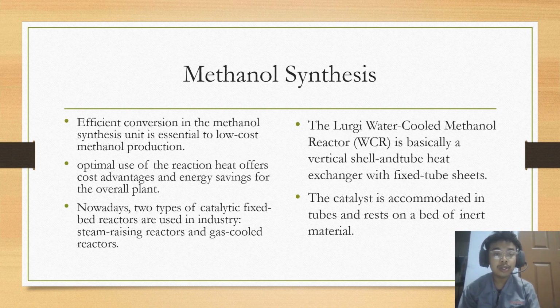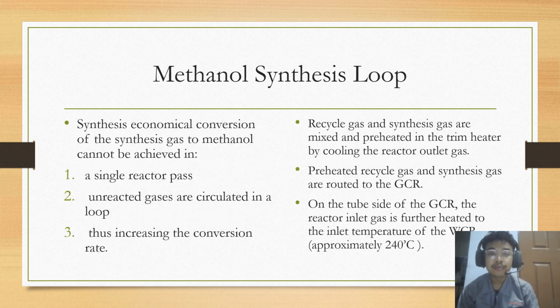The optimal use of the reaction heat also offers cost advantage and energy saving for the overall plant. Nowadays, two types of catalytic fixed bed reactors are used in industry: steam raising reactors and gas cooled reactors. The Lurgi water cooled methanol reactor, or WCR, is basically a vertical shell and tube heat exchanger with fixed tube sheets. The catalyst is accommodated in tubes and rests on a bed of inert material.